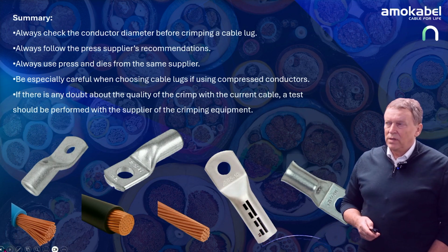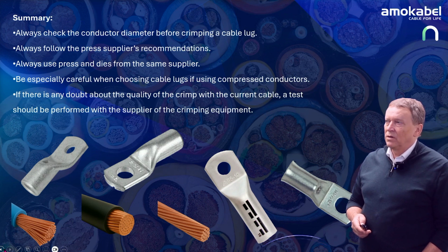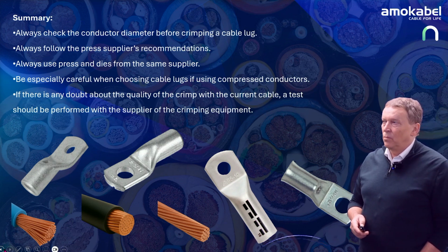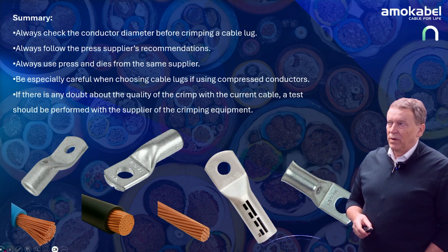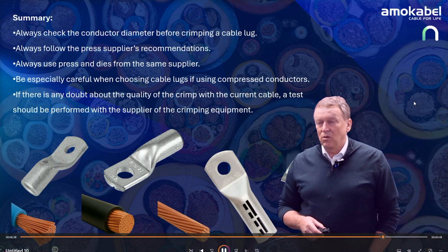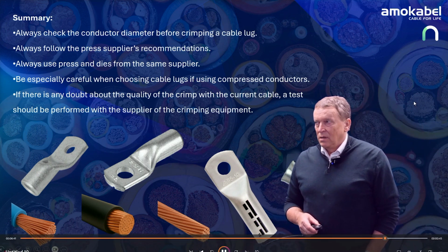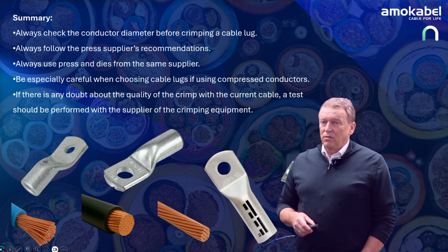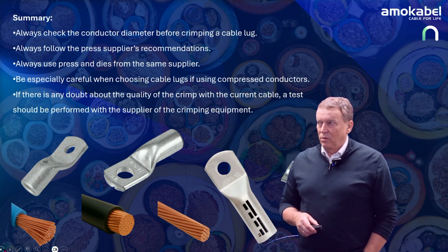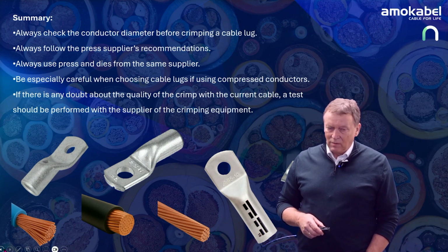Summary of this: always check the conductor diameter before crimping a cable lug. Always follow the supplier's recommendation for the pressing tool. Always use press and dies from the same supplier. Be especially careful when choosing cable lugs if using compressed conductors. If there is any doubt about the quality of the crimp within the current cable, a test should be performed with the supplier of the crimping equipment.